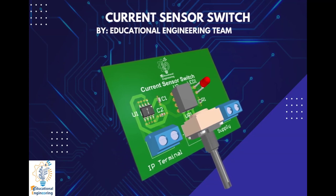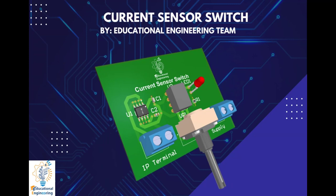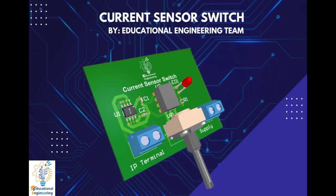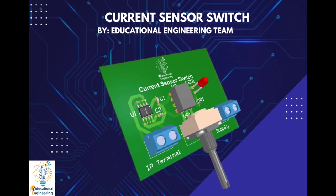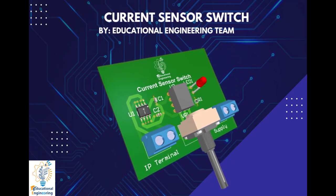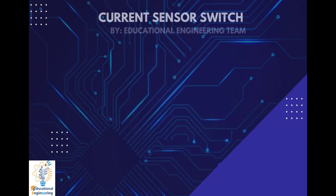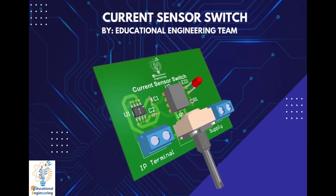Current sensors are used when there is a need to measure the amount of current consumed by a certain appliance or device. There are several methods to measure the current flow, and we are about to use the Hall effect in our current sensor switch circuit. The IC ACS712 is a simple linear current sensor, the most significant part of this circuit.